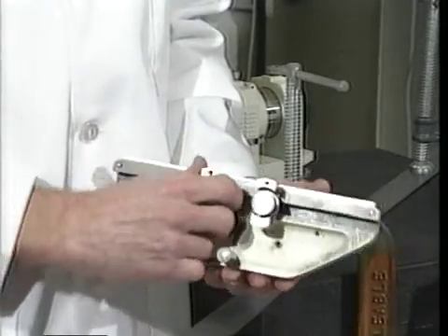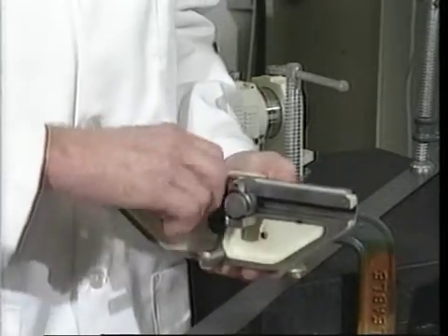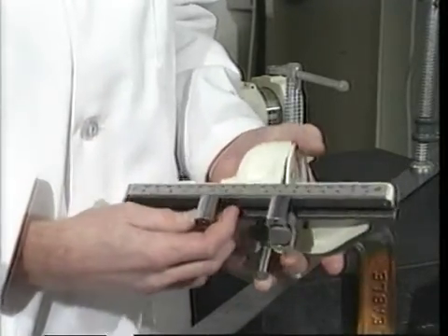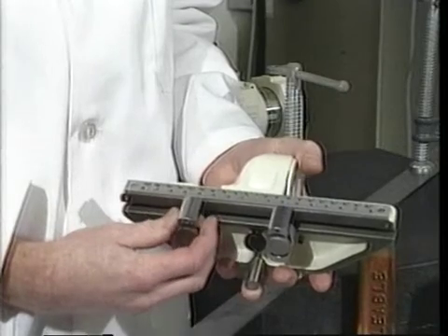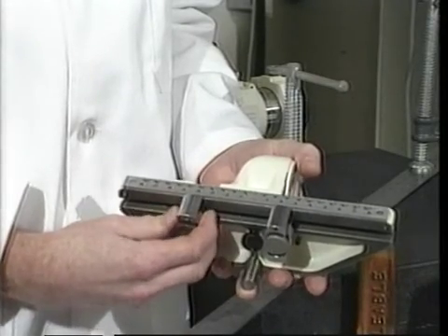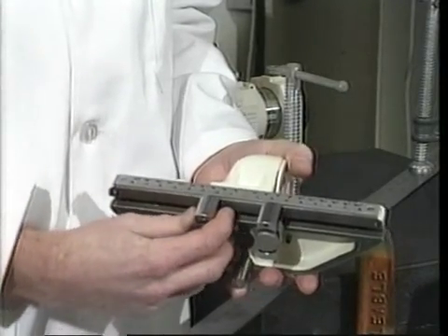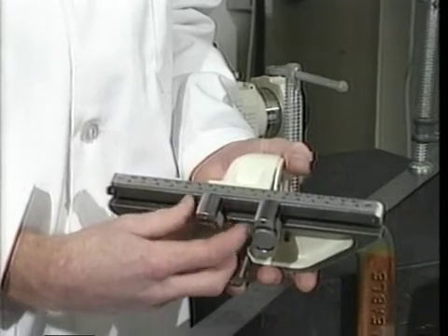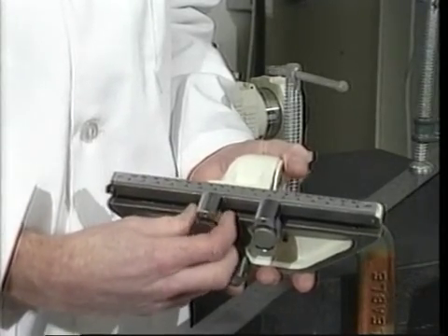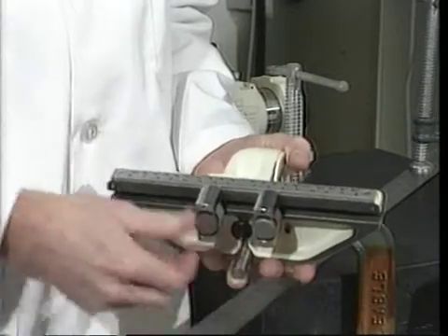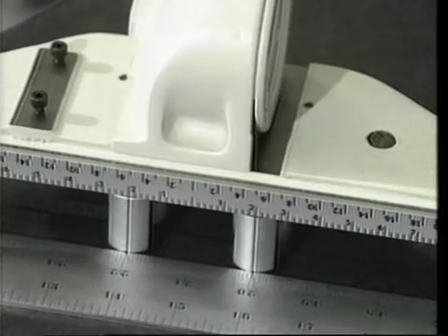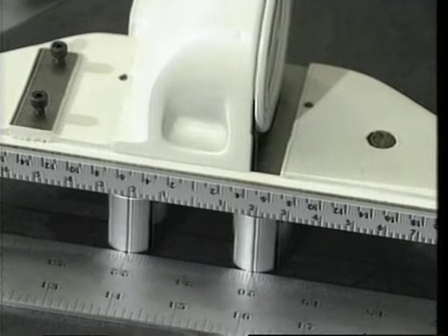Set the feet on the reflector sled to the desired spacing. Remember the trade-off nature of this parameter. Wide spacing of the feet can result in shorter wavelength variations being overlooked, while narrow spacing of the feet increases the number of measurement intervals and thus increases the chance of measurement error. In this exercise, the spacing of the feet is set to 2 inches to accommodate using the Union Jack pattern on an 18-inch square granite surface plate.